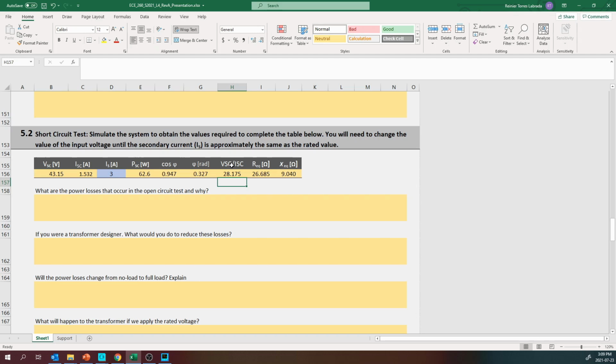Okay, and so then you go and find the transformer regulation. So what do you need to do for the transformer regulation? Of course, you're going to measure the voltage when you have no load. So you don't have to change the input voltage, but then you need to change the load that you connect to the circuit. So you need to modify the open circuit test. Right now you're going to add a resistor, an ammeter and a voltmeter on the secondary, and from that you're going to fill in this table.